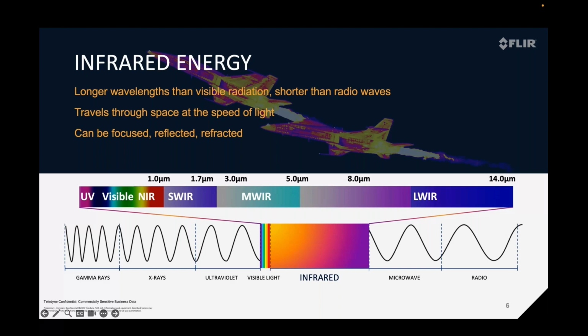SWIR is good for seeing through materials like glass. It's also useful for visibility through haze, capturing SWIR spectral information, and seeing through layers of paint with non-destructive evaluation techniques. I'd also like to point out that the FLIR SWIR camera is so linear in response that we can calibrate it for thermography applications starting around 400C, like I mentioned above. What I mean by that is calibrated per pixel for temperature.